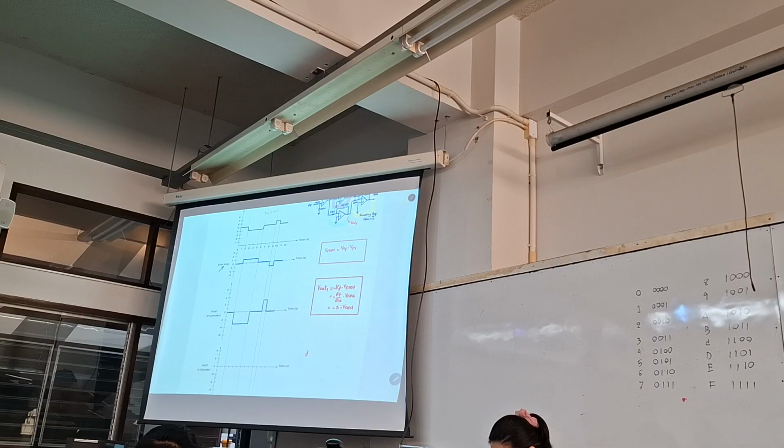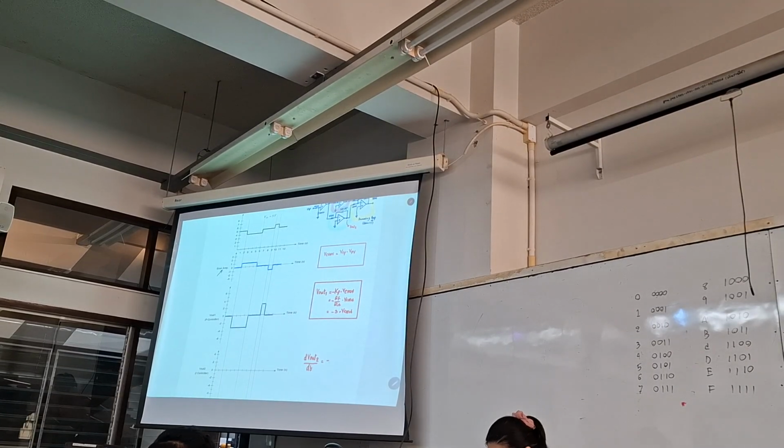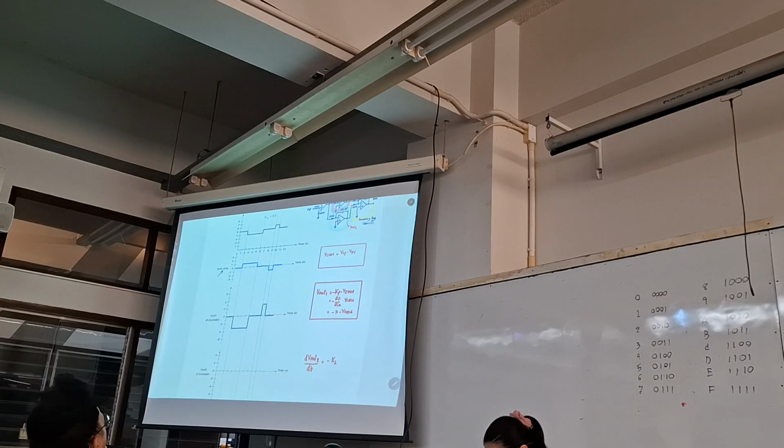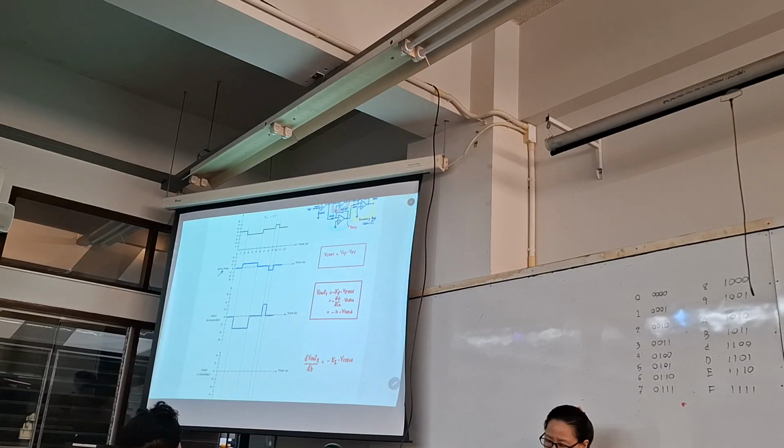So I could write dVout/dt equal to one factor, but this factor has to make a negative voltage because the input of the circuit is at the inverting pin, so we have a minus here: minus Ki multiplied with V. So we use the Ki value to determine the rate of change at the output of the controller.